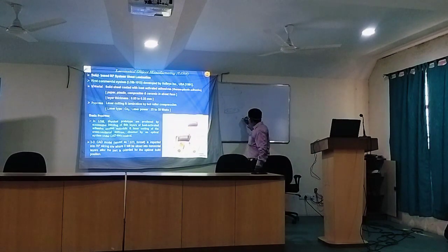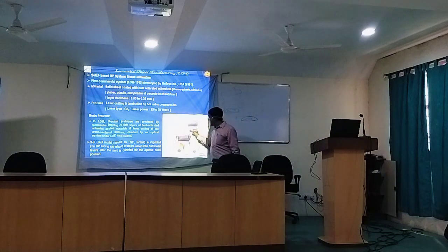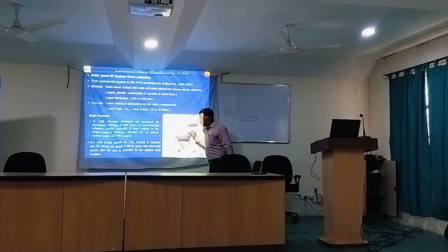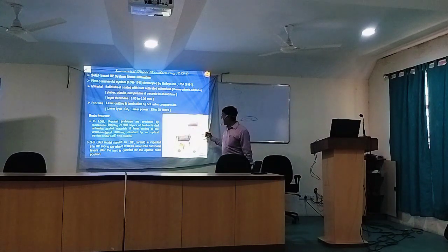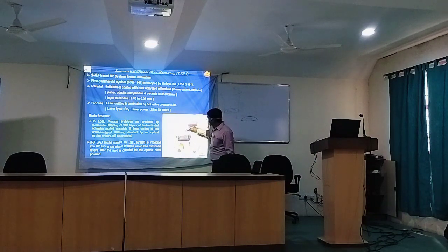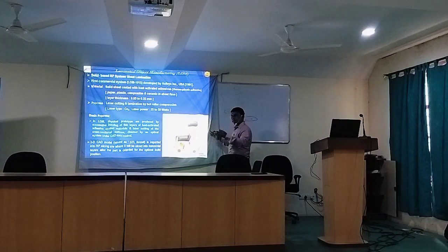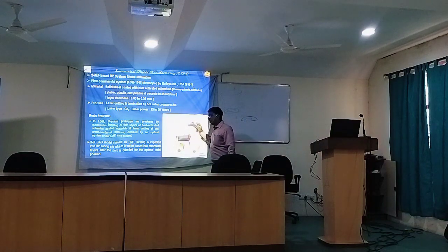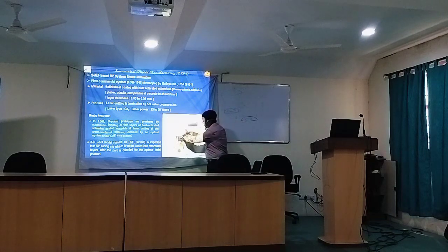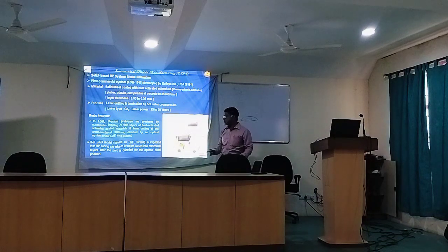The laser will trace over the outer boundary and the inner boundary, and due to the interaction of the laser and the paper, it will cut the outer boundary and inner boundary. Another thing we have to do in this case: depending on the highest size of the cross section, you have to cut one big rectangle, bigger than the highest cross section. Because whenever the platform lowers down, it lowers down with this total rectangular area.